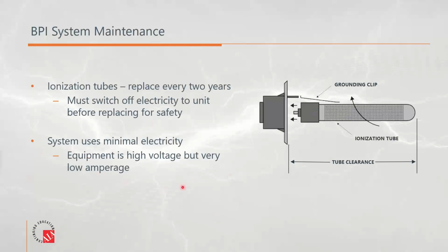Oh, and the other thing about this is where it gets into the energy side of things. When we look at what ASHRAE and CDC are saying about increased filtration and outside air ventilation, when you put these tubes into your system, there's pretty much a negligible air pressure drop, and they have very little amperage draw. So the energy impact relative to the quality of air that you're getting is very insignificant.